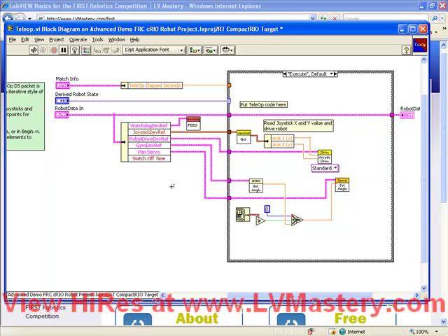and show you how you can pin down a wire as you're creating it. The first hint is do not click and drag. Click once and release your mouse button. Now you've started the wire. What you can do now is pin that wire down anywhere you want. If I pin that down now, then it's automatically started a second branch which I can control. So I could simply go and put that exactly where I want it and observe that the tunnel has been placed in an appropriate location, and I don't have to go back and move my wires around.